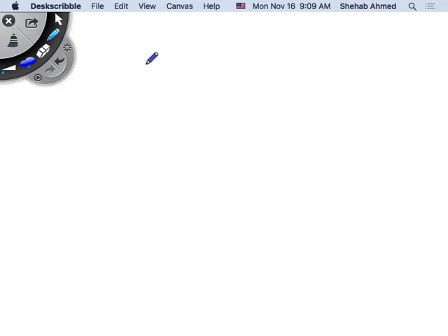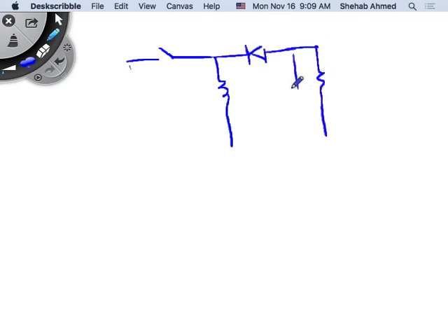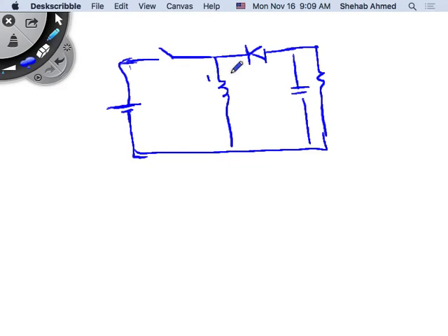And for the buck boost, we have our switch here, diode here. This is IL. What's the average value of diode current with respect to inductor current and duty ratio of the switch? Exactly, it's 1 minus d times IL.